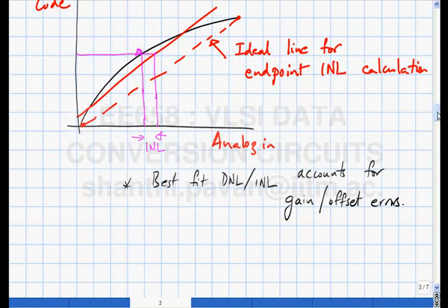So the eye is very, very good at catching local variations of color. But if the shade varies uniformly and slowly from one side to another, even by a large amount, the eye, it turns out, is a lot more tolerant of that kind of non-ideality than of DNL. For AD converters and D2A converters, similar definitions hold for the reverse process, which is D2A conversion. For both of these, which are involved in image processing, you will find that it's reasonably tolerant of INL, but the DNL will be specified to be very tight. So it will not be uncommon to say, okay, we need an AD converter with a DNL of only 0.1 LSB, but INL you can have 5 LSB, no problem.